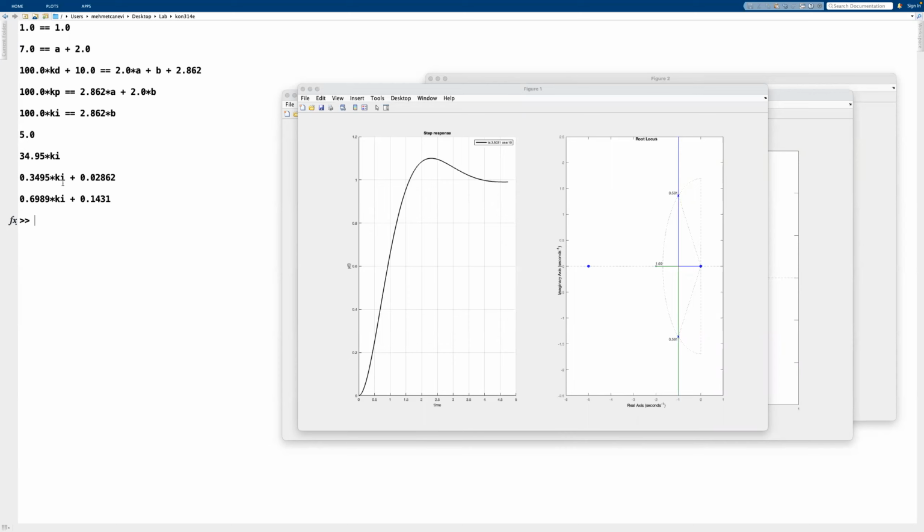Now, since the whole PID design problem depends only upon one unknown, which is Ki, this is actually quite strong if you think about it. Because if you would use any other numerical optimization solver, like fmincon or maybe a genetic algorithm or anything else, you would define Kd, Kp, Ki as unknowns, as parameters. So you would have x1, x2, and x3, and this would form a 3D space. And you would have a feasible region, and then there would be the optimal region. You might have global or local optima, etc.